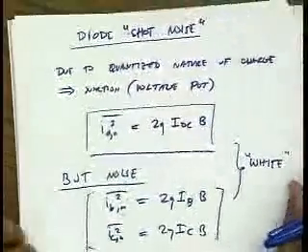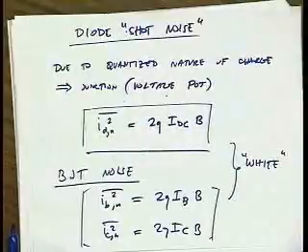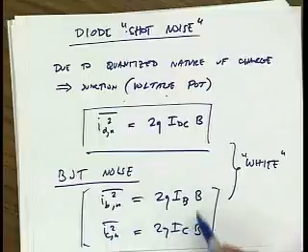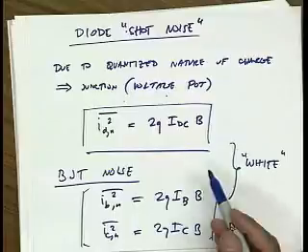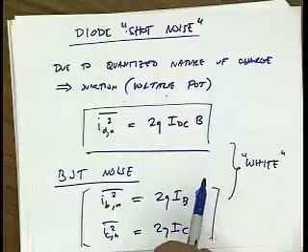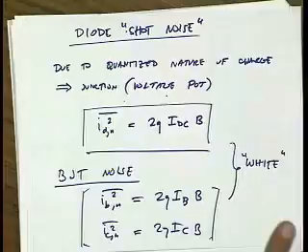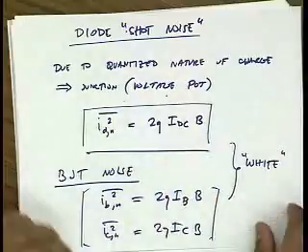So it's not like in MOS transistors where you have a certain amount of correlation between the base and the... Yeah, very good question. We'll talk about MOS in a moment. There's probably a very small correlation, extremely small, because some of the collector current is due to the base current injection, but it should be very small because remember it's a reverse bias junction. It's also a minority carrier, so the correlation should be very small.